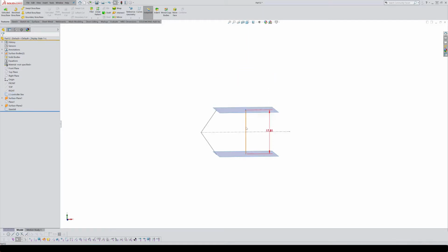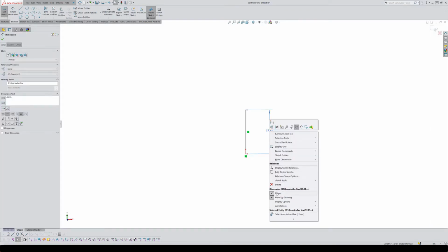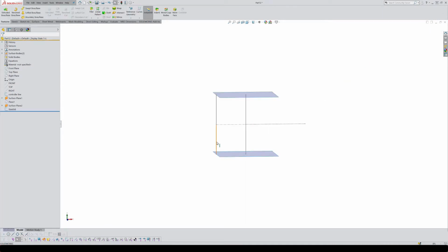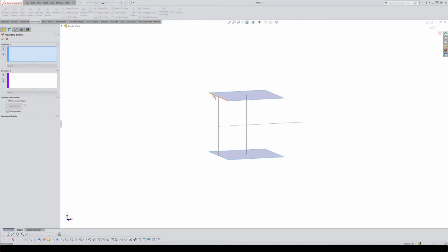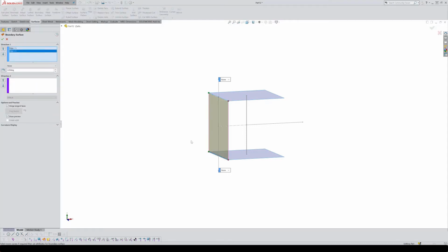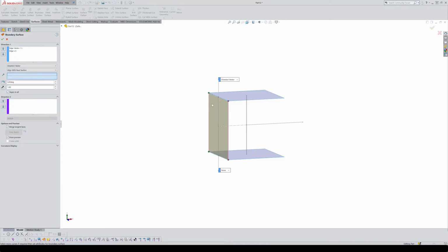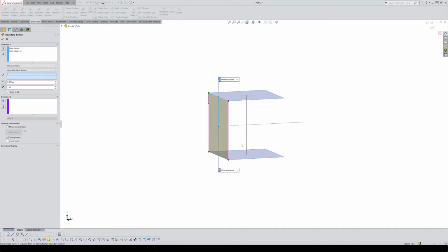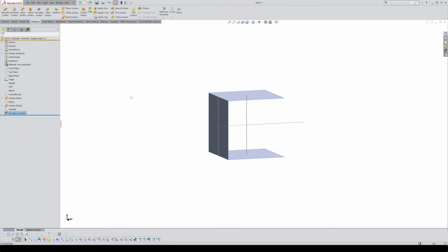All right, before I continue here, let's put the line back to how it was. So you're no longer driven and you'll be 24 inches. So it'll look just like that again. Okay, the next step, we need to create a boundary surface between this edge and this edge. But here's a kicker. For the direction vector, I'll select this line, so that is putting its tangent influence into that. I'll select that line for there, select direction vector again, and then select this bottom line, meaning that this boundary surface should follow those 2 lines. So you may see where I'm going with this.